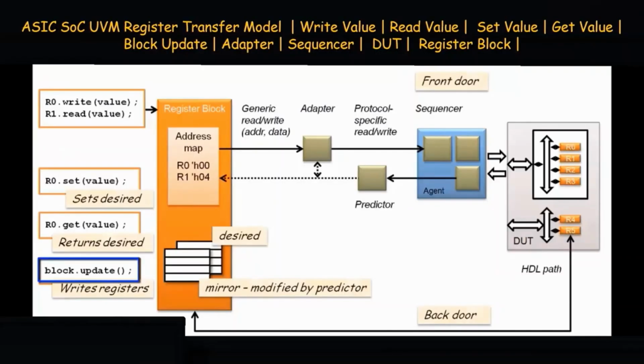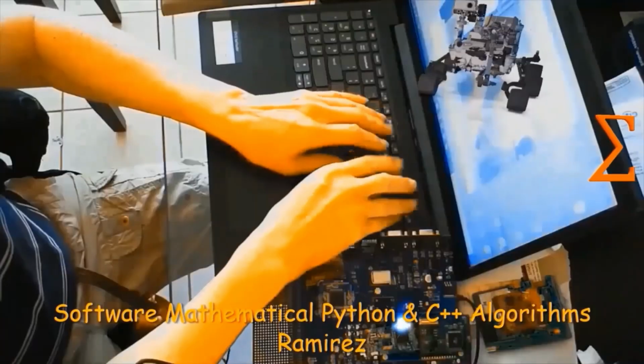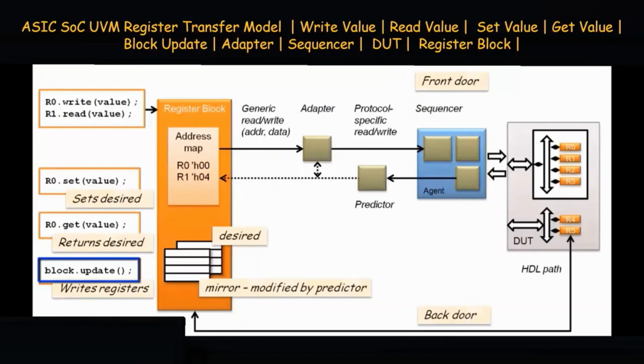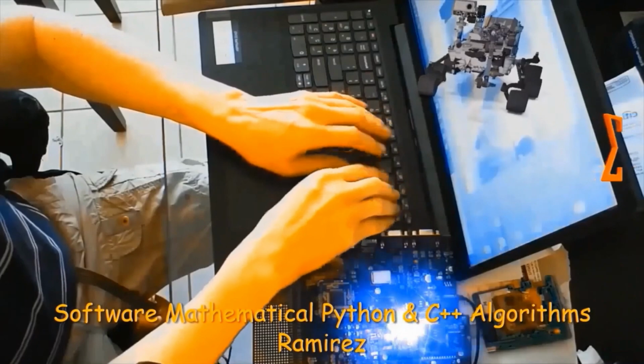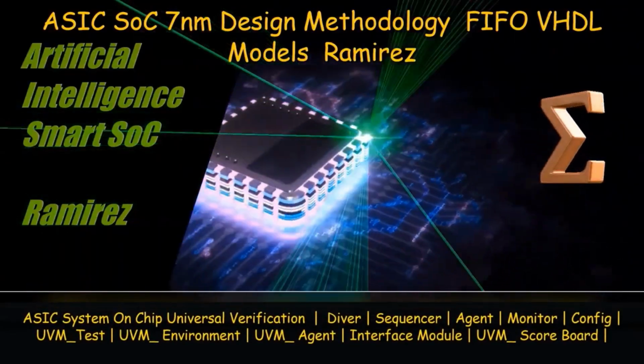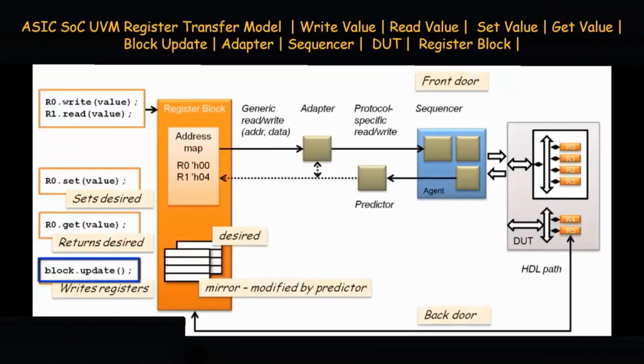As stated before, the register model provides a layer of abstraction, reading and writing registers, an object instantiated between sequences, scoreboards, and agents that abstracts details of control and status registers in the DUT, permitting sequences and scoreboards to access registers by name.